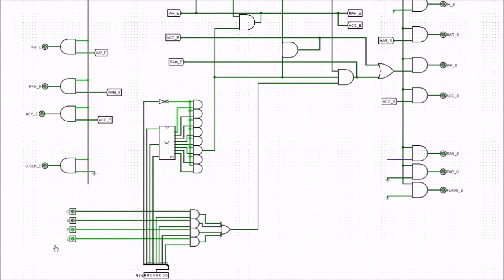So you can see here at the bottom we have our carry, our A is greater, our equal, and our Z coming in. Those are going through these AND gates here and then through an OR gate. Now the other pin of these AND gates are connected to the first 4 bits, so this is going to be our carry, our A, our E and our Z for these 4 bits.